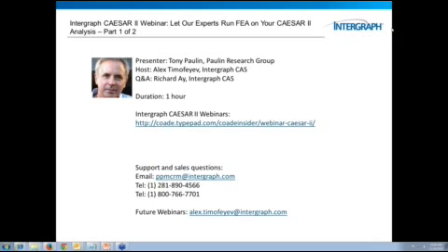Contours, tees it evaluates. The FEA tools modeler goes through the Caesar model and, if you ask it to, it pulls out all of the B31 stress intensification factors for branch connections and replaces those models. So it takes out the tees and replaces the stiffness model and the I factor model with more applicable data. So the idea is that the first thing we wanted to do was to get the calculations that we make for our bread and butter every day. We wanted to get those right first. And so that's what version 1 of FEA tools does.